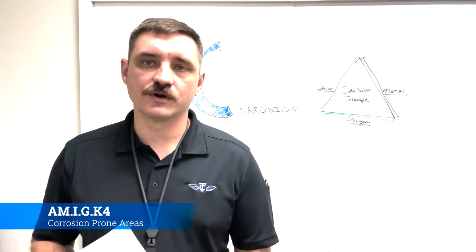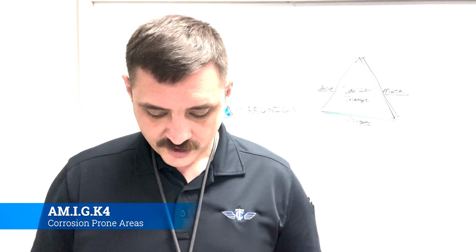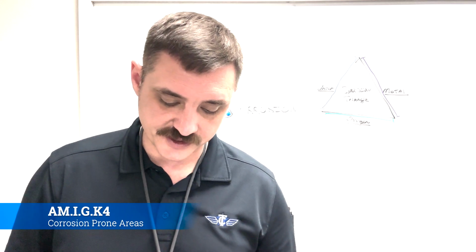Okay, so let's talk about corrosion-prone areas in aircraft. We're just going to go down the list, and we'll splice in different examples from the Lear or the Aztec. So, exhaust tail areas. Both jet and reciprocating engine exhaust deposits are very corrosive and give particular trouble where gaps, seams, hinges, and fairings are located downstream from the exhaust pipes or nozzles.